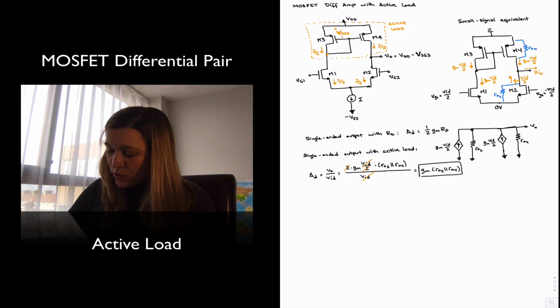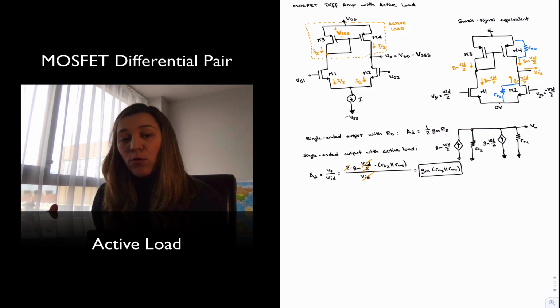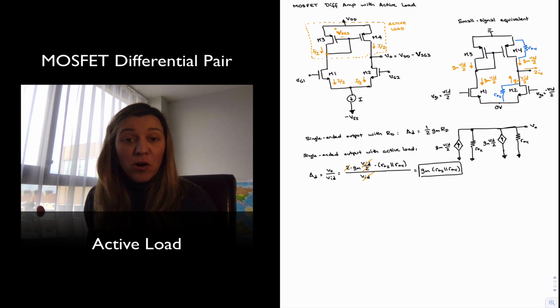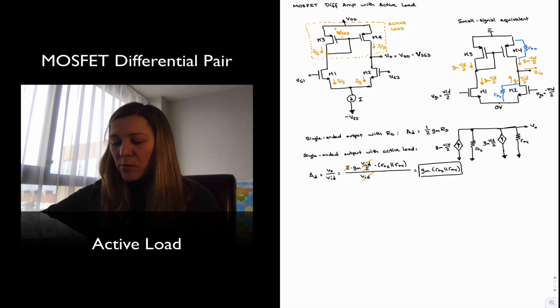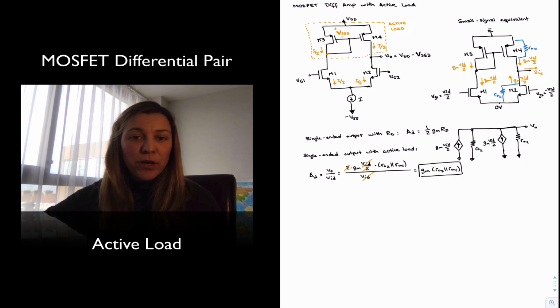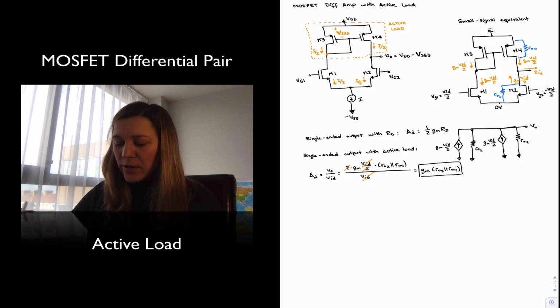And that's an important result, because notice it will be what we will expect from a balanced output, right? The differential gain will be negative, but GM in absolute terms, it will be GM times the resistance connected at the drain. We typically approximate it as RD, but it should be RD in parallel with little RO, right?